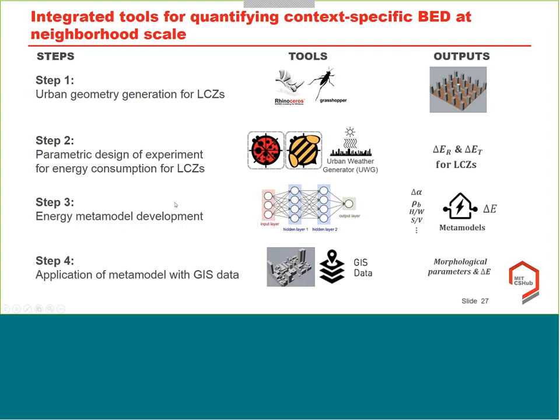What we do then is some statistical analyses on those to understand the attributes of all those different analyses that we ran, and then we can use that to develop these statistical meta models. So then we can say we have a lot of confidence in the results that we can quantify that change in energy, including both radiation and ambient temperature, for a change in albedo, okay? So we get this statistical model that allows us to do these energy calculations for a particular climate, but for a range of different urban morphologies.